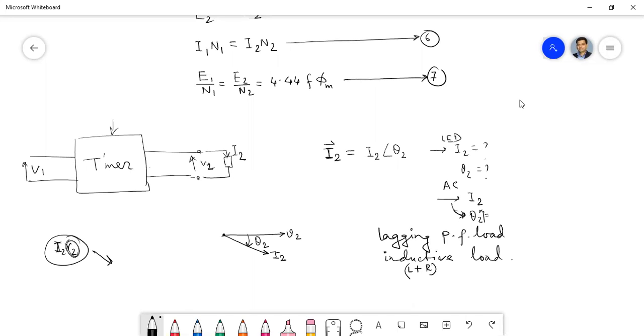It's not a vector or phasor, isn't it? R2 is just a number. So it will give some scalar multiplication with I2. Therefore, it will be in phase. In phase means you can also draw it in parallel with I2, but it will be scaled by R2. It's a different unit: I2 is the current, but I2R2 is a voltage. So you have to draw I2R2 like this. So this is one voltage component.